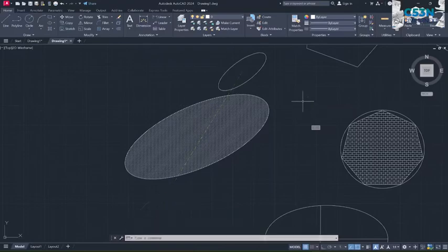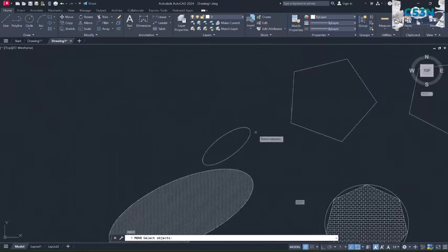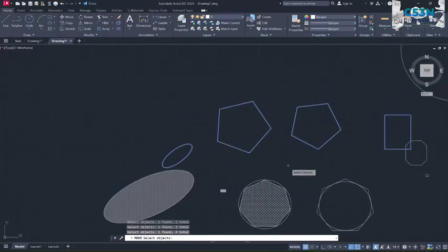The last thing we will be talking about in command move is that if you want to move multiple objects, type M, enter or space. So select your first object, left click. Now do not just right click to confirm selection. First select all the objects that you want to move. So this is our second object, left click. Now to confirm selection, right click.